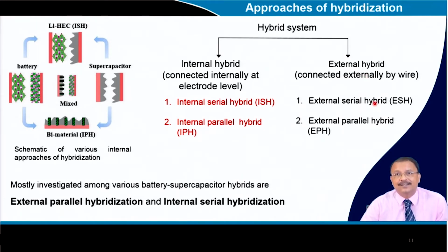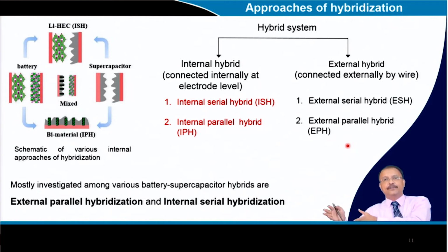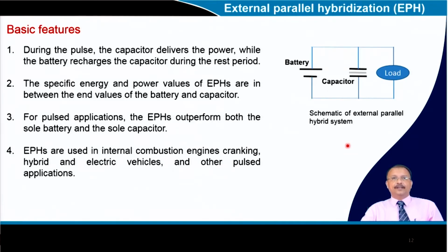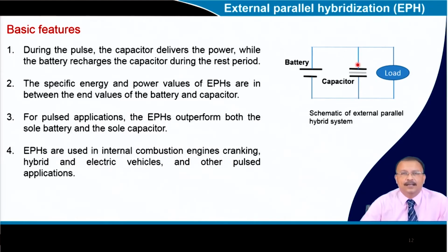So, they are using external serial hybrid or external parallel hybrid, physically considering a capacitor stack and the battery stack, and then they are connected. So, this is external serial hybrid. So, this type of thing is being investigated quite rigorously, and the basic feature if you go for external parallel hybrid is a battery and a capacitor connected with the load like this.